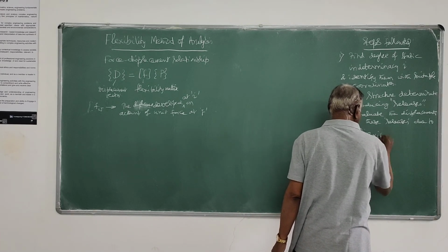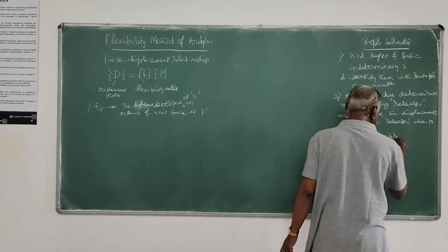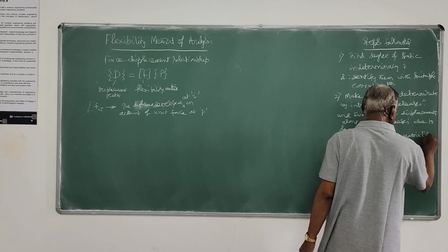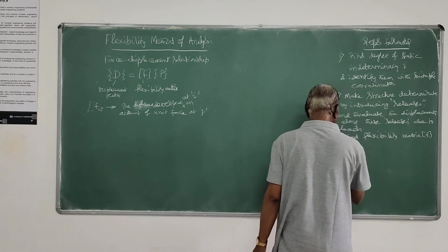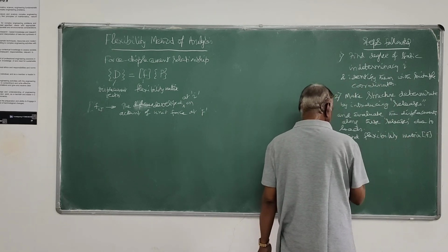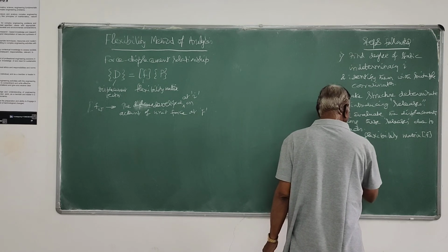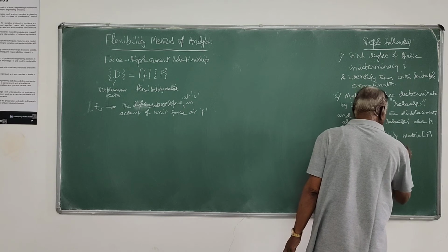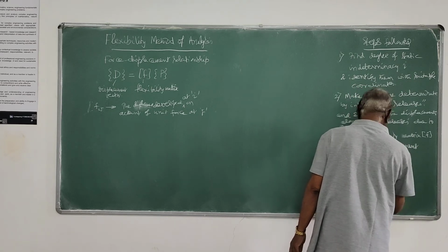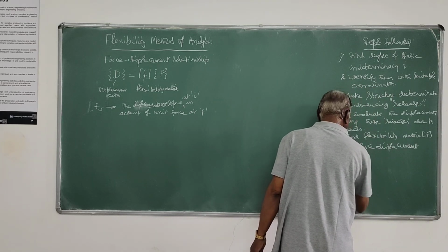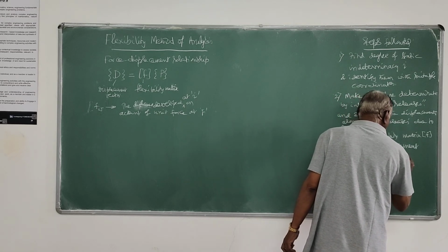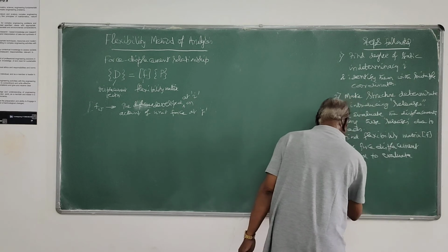Then third, find the flexibility matrix F. Then after finding this, use the force displacement relation to evaluate the redundants.